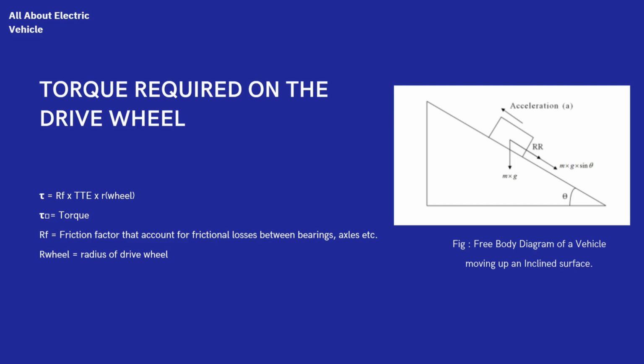The total required torque on the drive wheel can be obtained by directly mounting a motor with the required torque value on a differential of the vehicle. Alternatively, a gearbox or chain drive can be used to magnify a lesser torque to the required value before it drives the wheel. The choice of the method depends on the design of the vehicle and the desired torque and speed characteristics.